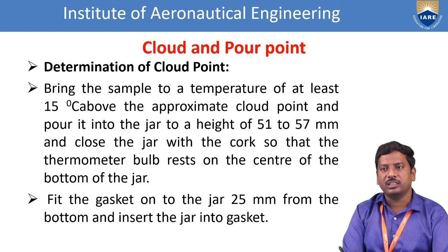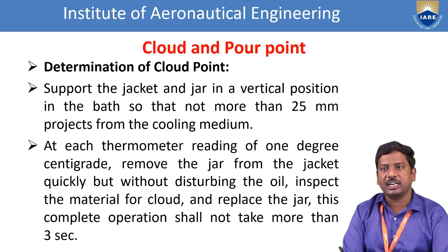Now fit the gasket on the jar 25 millimeters from the bottom and insert the jar into the gasket. Now support the jacket and jar in a vertical position in a bath so that not more than 25 millimeters projects from the cooling medium. At each thermometer reading of 1 degree centigrade, remove the jar from the jacket quickly but without disturbing the oil. Inspect the material for cloud and replace the jar. This complete operation shall not take more than 3 seconds.